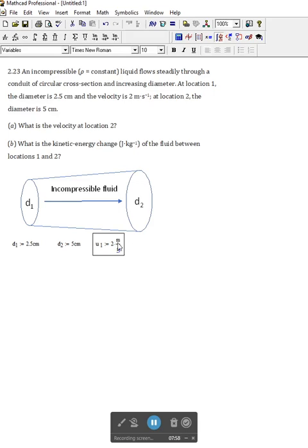One of the things you need to notice though is that, for example, MathCad will mess you up if I define a variable as M. A lot of times we use M for mass. If I tried to define a variable M for mass as 5 kilograms, what MathCad thinks I'm doing is defining 1 meter to equal 5 kilograms.